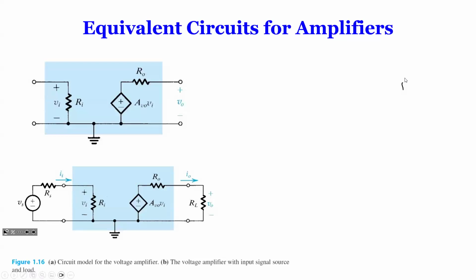The amplifier isn't really working because you got voltage coming in, 999 is here, only like 1 is here. You're not really amplifying. You're amplifying a very small portion of your source. That's no good. So that's why in the future, if you look at any sources for quality, the smaller the internal resistance, the better the source.